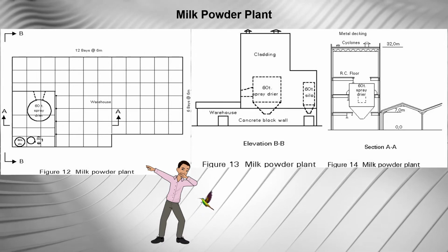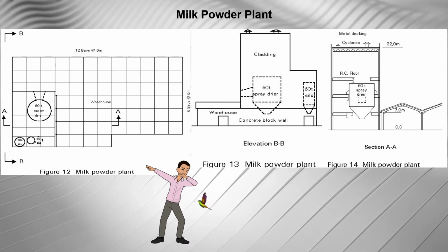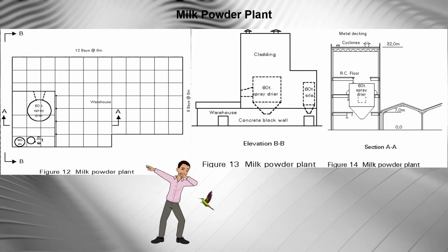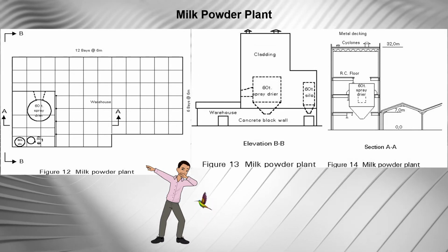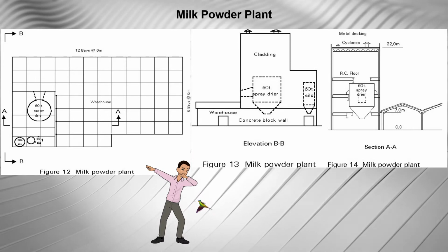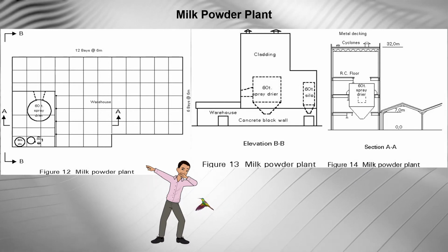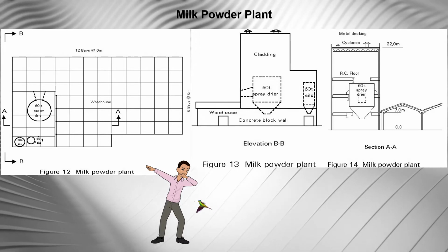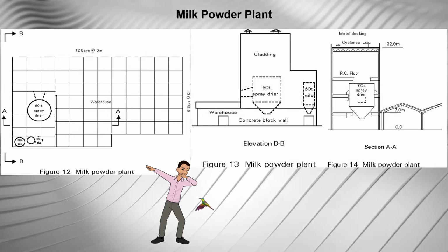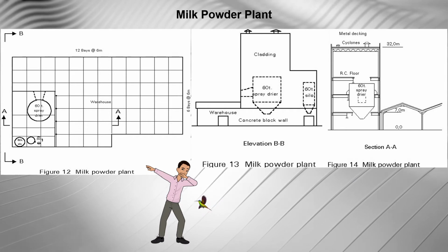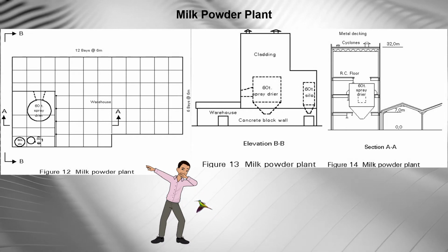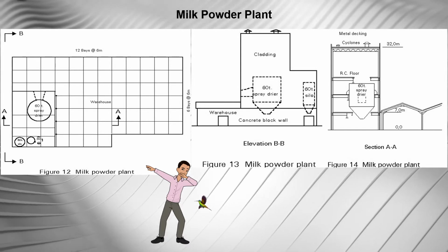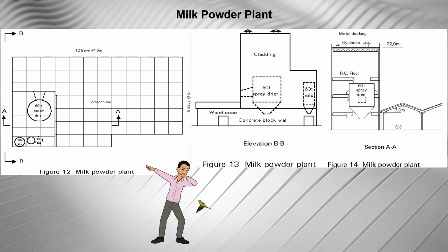The floors are lightly loaded except for ancillary plant and the spray dryer, which in operation weigh 60 tons. There is an appreciable explosion risk from the finely divided milk powder. Strong explosion ducting with an exterior blowout panel intended to control the direction and result of an explosion is incorporated in the dryer, and provision for this facility is made in the tower steelwork.